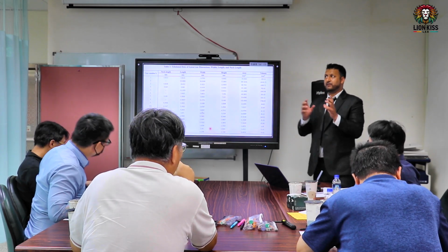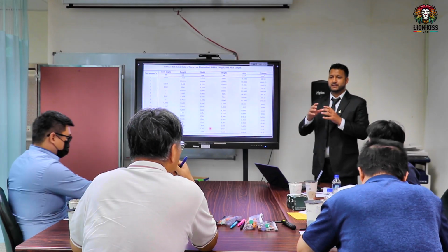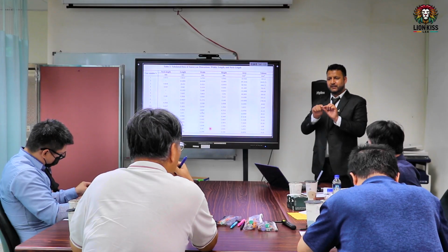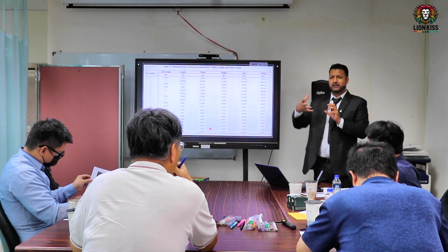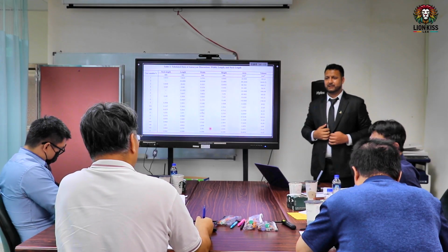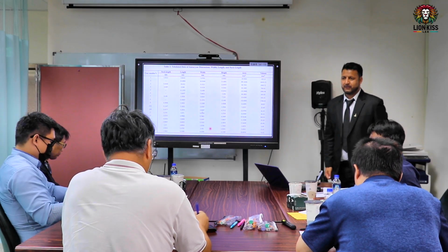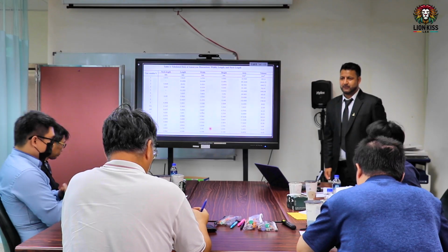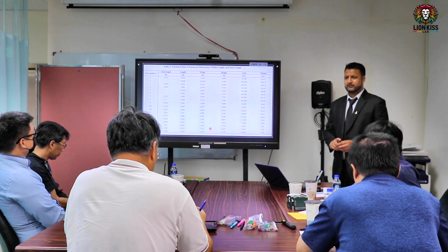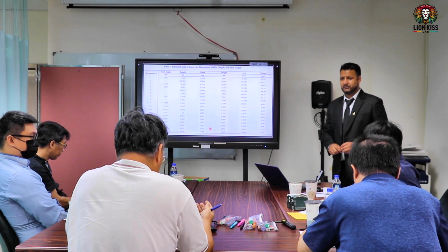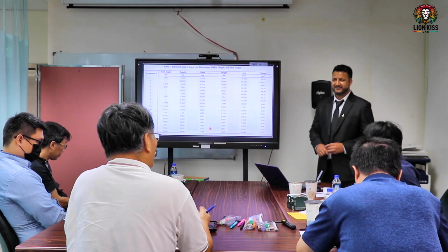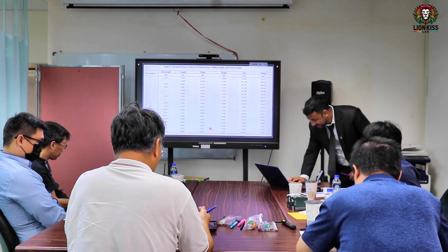No, like the turbulence showing after stenosis, the OSI is very high because when it's a very high stenosis, the jet flow is very high and that also makes a turbulent-like flow. It's showing as a high OSI. Okay, then you need to make it clear in your dissertation that you are not using a turbulence model, only laminar. And you should also provide the Reynolds number to justify it. Otherwise, people will question.